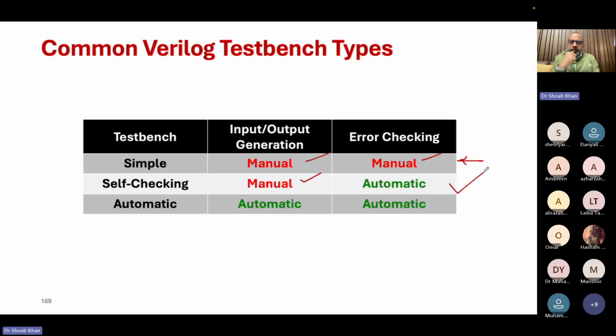And then comes a thorough approach, where you put in billions of inputs and outputs, and you let it run for days. You have designed an environment, a pretty complex design, which would take many days to run. Wherever there's an error, it should log that for this input, this is the wrong output. You have a log file, and the log file should tell you how many mismatches you are getting.